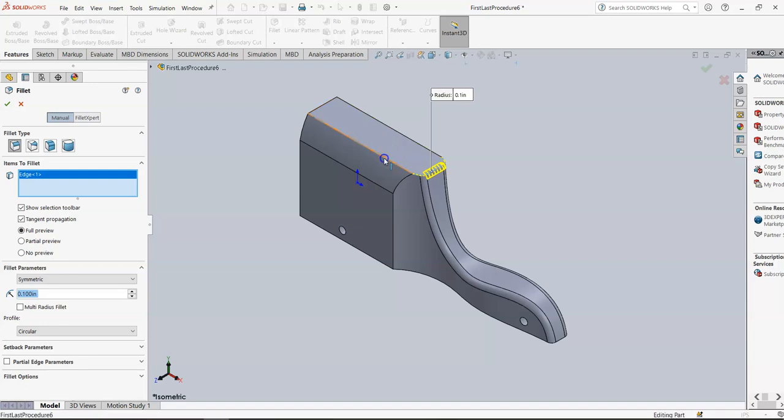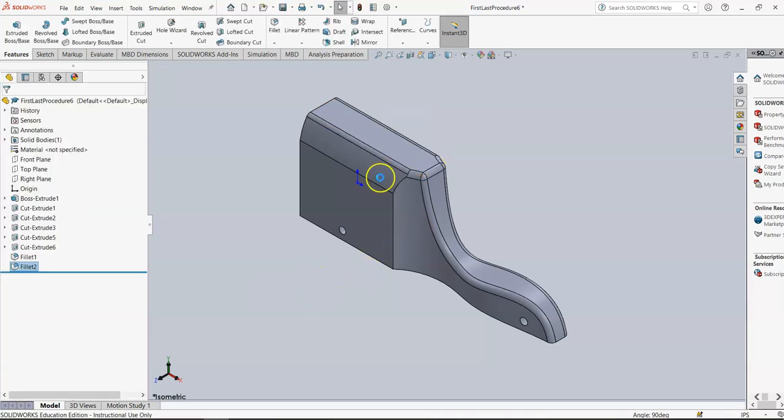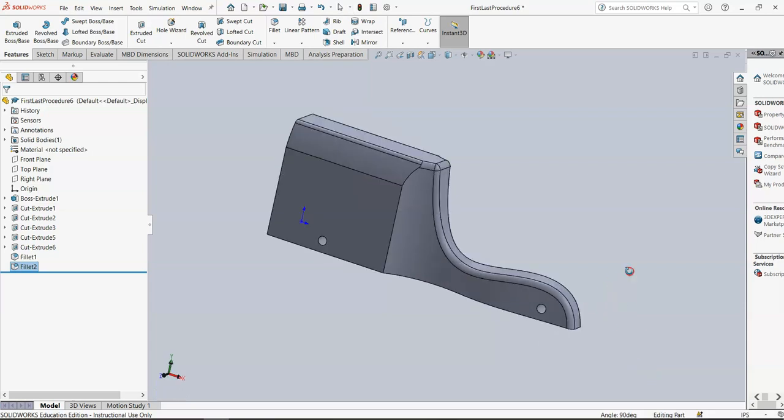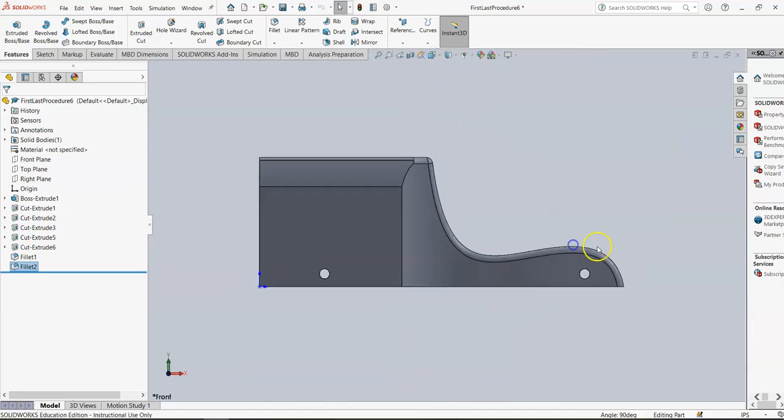So the problem is you can't fillet everything. If you start to fillet too much, you could run into some issues. So if you're going to fillet anything, this area across the top is usually okay. This area through here is usually okay. Let me show you where you can't fillet. This front edge, because in order to fillet that, the bit would have to come down and round around the front of it, and we know that our bit can only travel up and down.